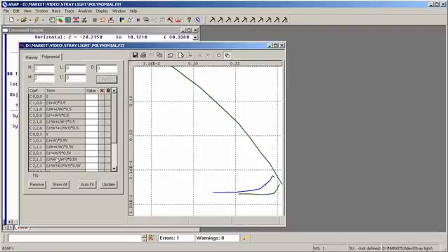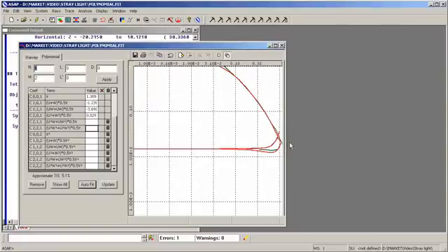Now the fitting utility within ASAP can only fit 10 terms at a time. And so we're going to select the top 10 to start with. 1, 2, 3, 4, 5, 6, 7, 8, 9, 10, and lock the rest of them down. We go ahead and select Auto Fit. This represents our fit, which looks pretty good. We'll often find that several iterations give us some improvement. And this is actually looking very nice, but we'll go ahead and unlock the other coefficients as well and try doing just a little bit better. Auto fit.